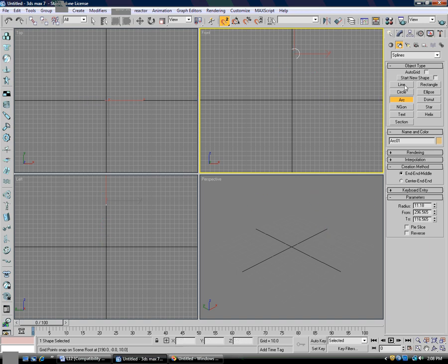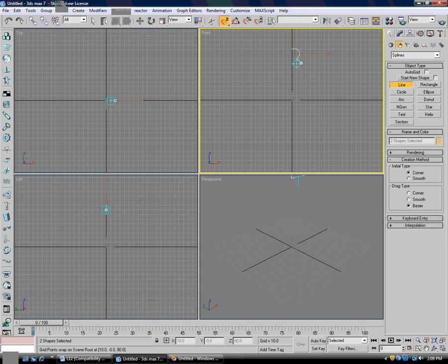And then I am going to have a line. So now you can see the endpoint of this arc. I am going to select that endpoint of the arc, click there and release the button and move the mouse to the endpoint of that line and click there. So you have that line and right click. After having that line I am going to have another line. Starting point is this, click there, release, click the endpoint, release, right click. Now you have that part of the line.